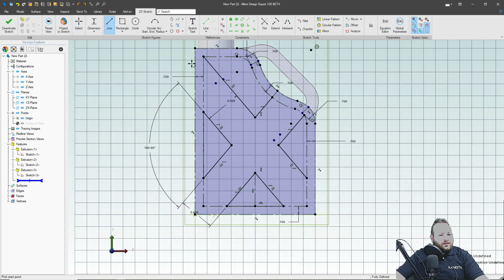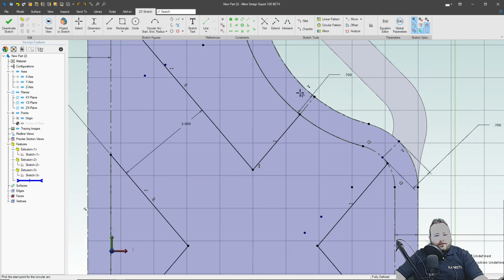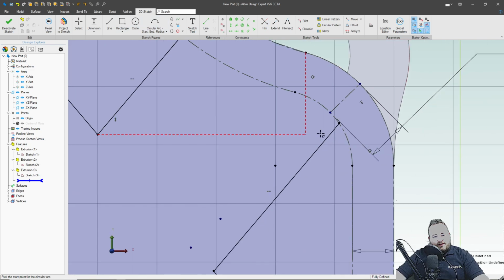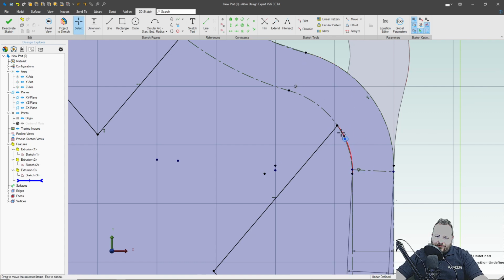Let's go with there to there. I'll make an arc. And sometimes these arcs can be a little bit stubborn, but I think when you click on a point, yeah, you know what, let's trim that. Right there, perfect. So trim that so we have an enclosed section there. We want to enclose this section. When we select a point that's on the arc for our 3rd point, then it works. It won't be defined if I select a random point because this point needs to get defined.